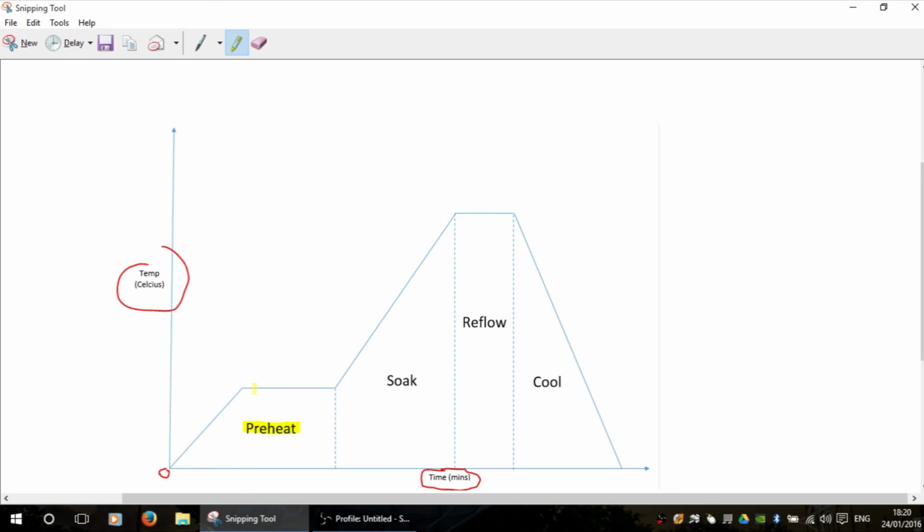So preheat is a very, very, very important part of the process, because without it, it means we have to subject BGAs to higher temperatures for longer to absorb necessary heat into the rework area, which can cause us to damage things like the BGA or the board, or kill the BGA altogether, which of course is not what we want to do. So that is what we use the powerful bottom heaters on our rework stations for. That's what we use them for. We use them to absorb heat into the board and the area we're going to be reworking.